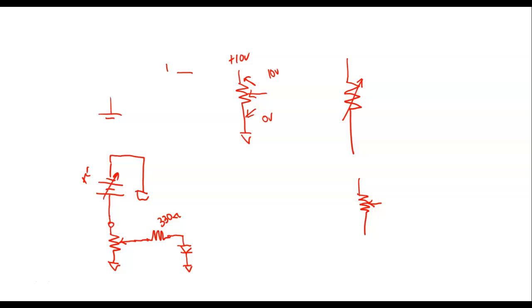Or common. Yeah, and out there in the real world, odds are you're going to call this a ground, but I really want you to understand the difference between a ground and a common. So if I use this trainer right here, at both these trainers, the power supplies are ungrounded. So in these trainers, that little lead, that little black one, they say ground is not ground, it's a common.